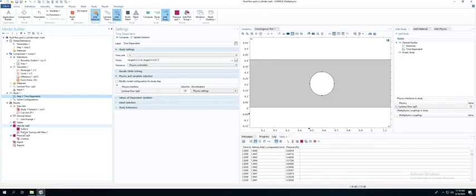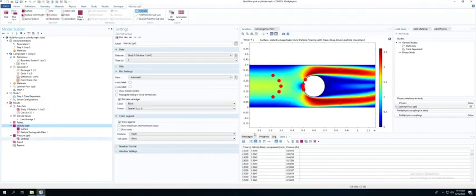So here we were defining the velocity and the pressure, and that's what we looked at, and we wanted to know what that velocity was as I increased the diameter of this stationary object. Then I can take those average velocity measurements across this cross section, grab those measurements at each point, write those down, and include those in my report.